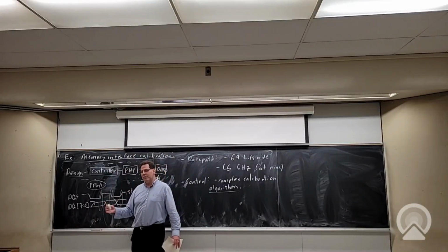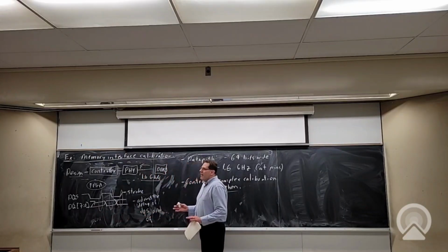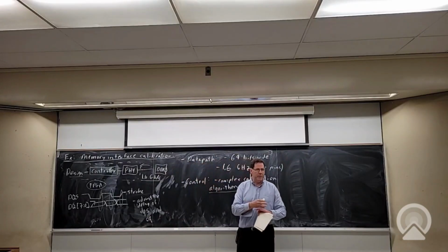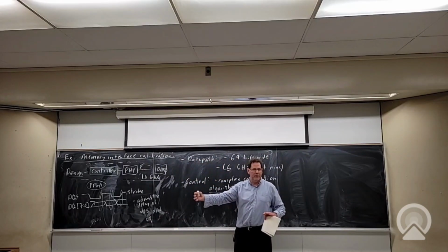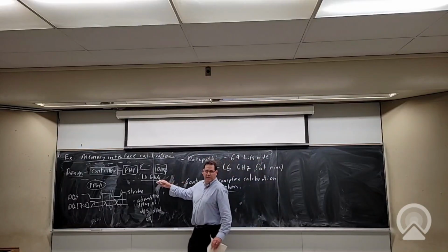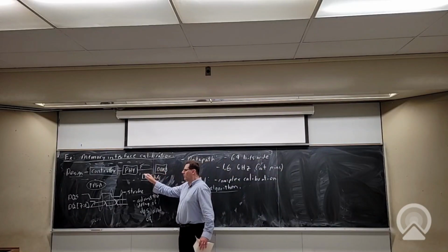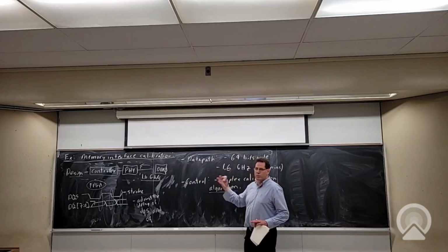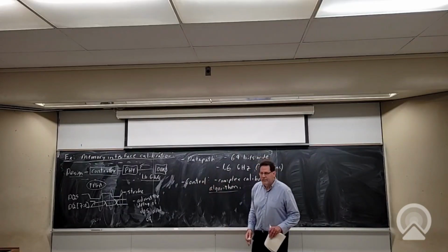This is why source synchronous standards are used to talk to off-chip memory. As you're going to see, this calibration algorithm is necessary to make them run at high speeds. And if you start moving this DRAM chip further and further away, where the traces on the board get less and less predictable, your speeds will go down. So this is a good way to talk to memory as long as it's relatively close. And it's one of the two dominant ways we talk to things quickly.